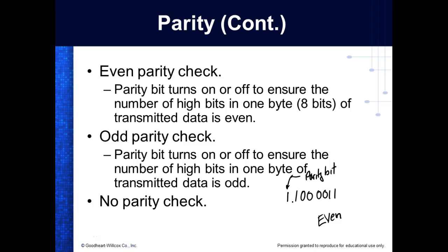But let's just look at 2. Y'all see one called NAK, N-A-K? What code is that? Yeah, negative acknowledge. And then you see ACK, right? So what would happen is that if the receiver got the wrong parity, it could send back a not acknowledge. It would send back that code for a not acknowledge, and then the transmitter would retransmit the last data. And we call this handshake. So the 2 devices, you send information to the receiver, and it lets you know if it's okay or not okay.